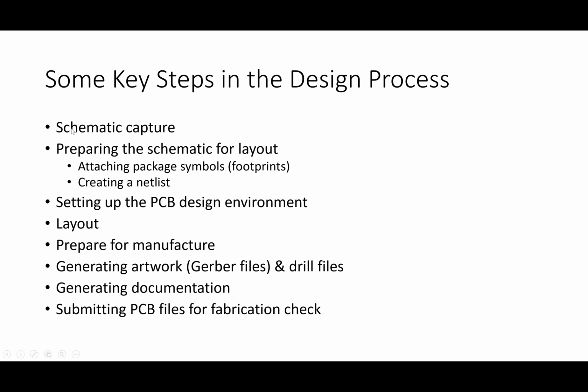All right, so you'll do that in OrCAD. What you then do is you get that schematic ready for layout. Chandan will walk you through that process, basically how you attach package symbols, specifically what we call footprints. In other words, how we actually go about putting in the specific ways in which the chip itself or the component itself is laid out. So there's some basic things, mechanically, that we need to get you introduced to understand this piece.